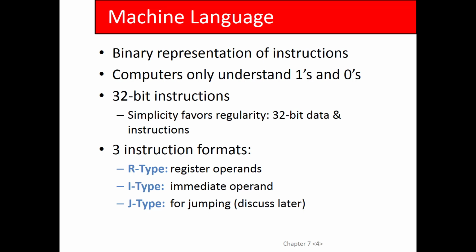So ultimately, if you're doing graphics, you're bringing pixels into the registers, you're processing the pixels, and then you're storing them back out, right? So the registers are a temporary holding spot for data for the processor to do computation with, right? So that's called a load store architecture. You load in, you process it, you store results out, okay?